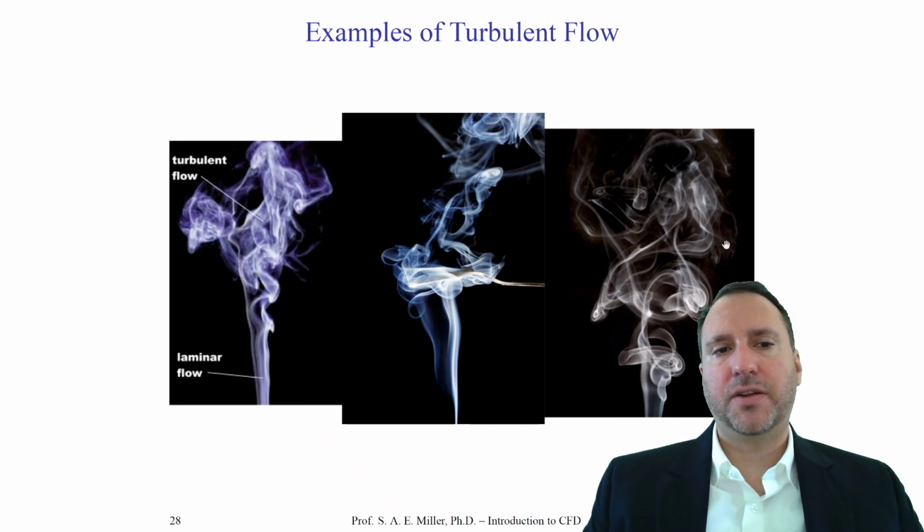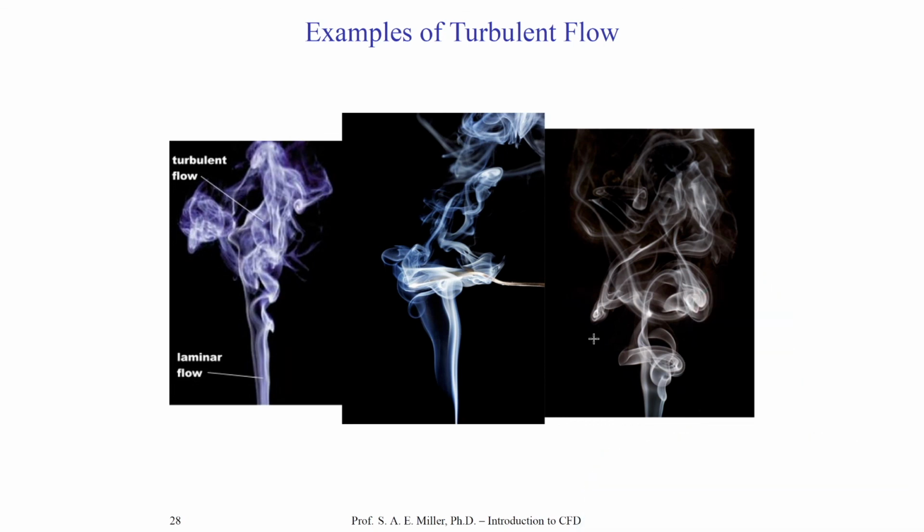Here's just a higher Reynolds number and closer view of that turbulent wake. You can see all these beautiful structures. And in this class, I talked a lot about what are large-scale structures and small-scale structures. And this is a great example because it's a relatively low Reynolds number flow. And so the turbulent cascade isn't very large. That is, the distance, the number of decades between the integral scale and Kolmogorov scale are very small.